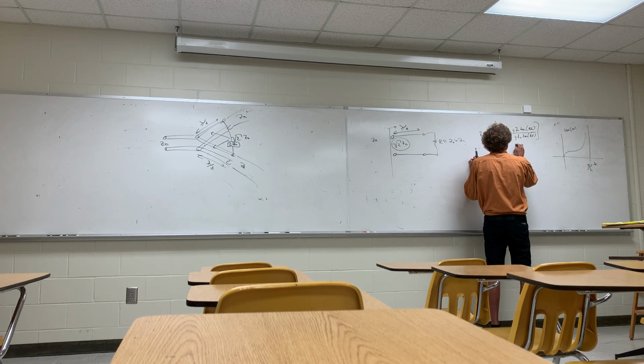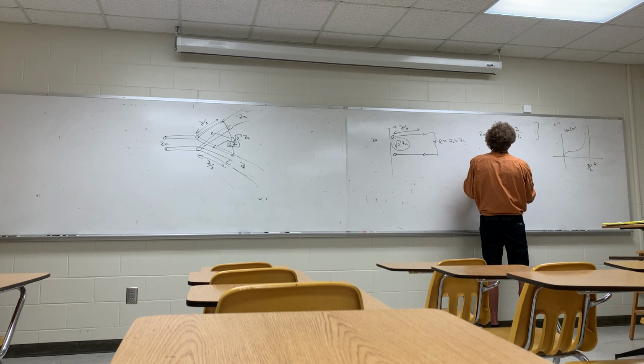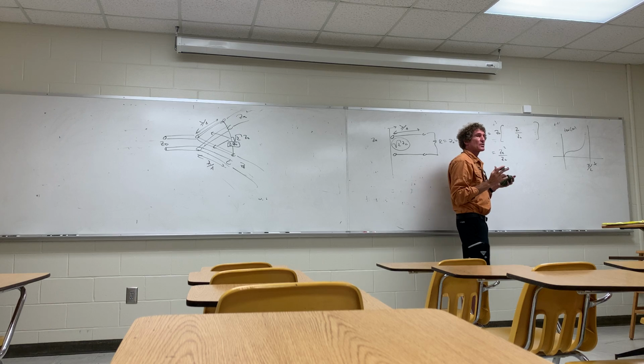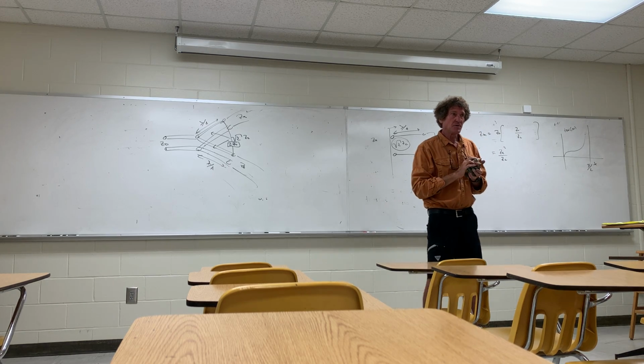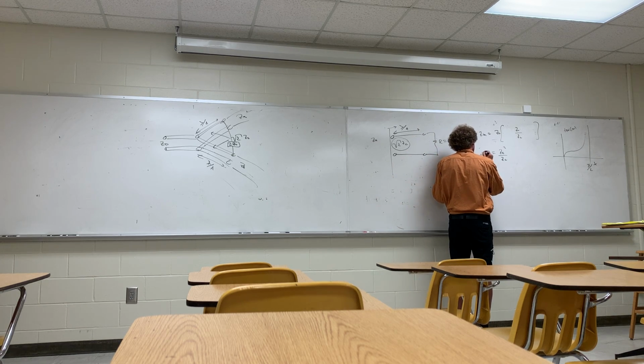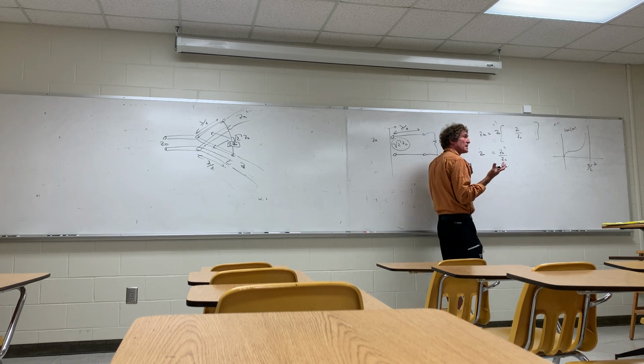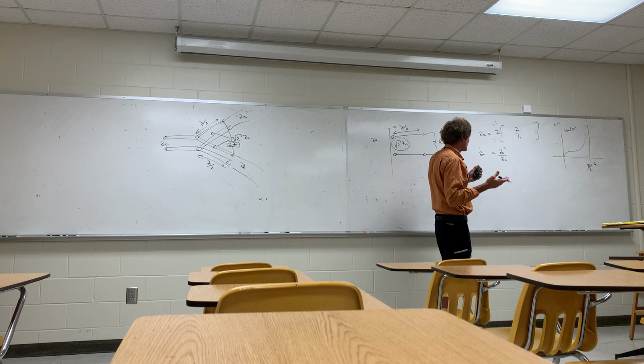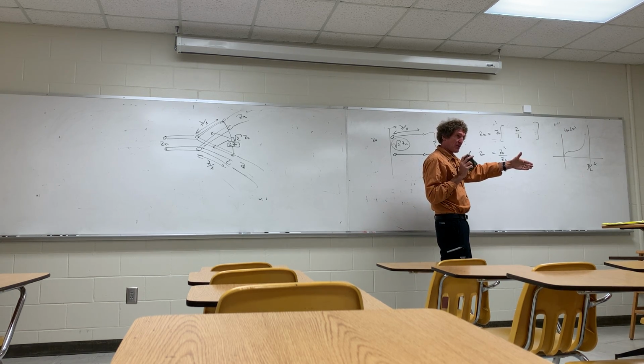And we can ignore the j's. And we can ignore the tan. So now what I have is Z naught squared over ZL. Now that's called a quarter wave transform. You can calculate the value, and this would be Zn. If you wanted the value of Zn for any ZL, you can calculate, if I take ZL times Zn, take the square root of that, that's the characteristic impedance I'd want for that line. Y'all follow me on this?